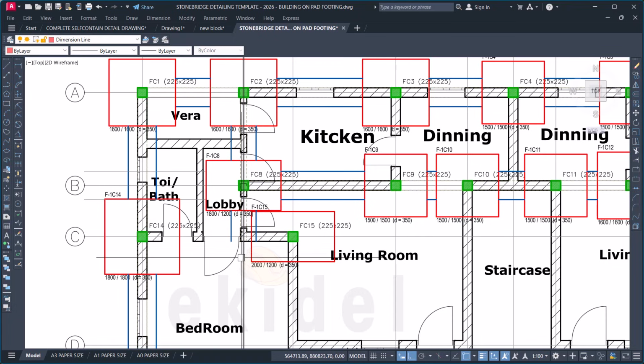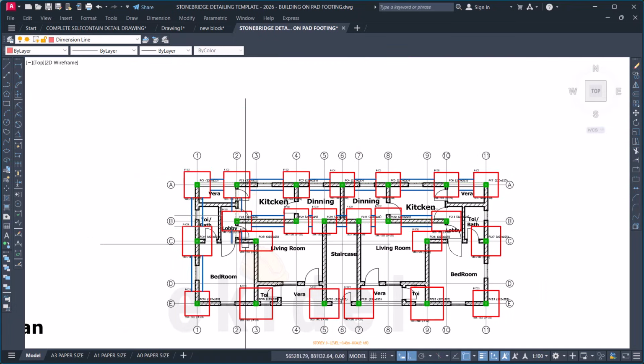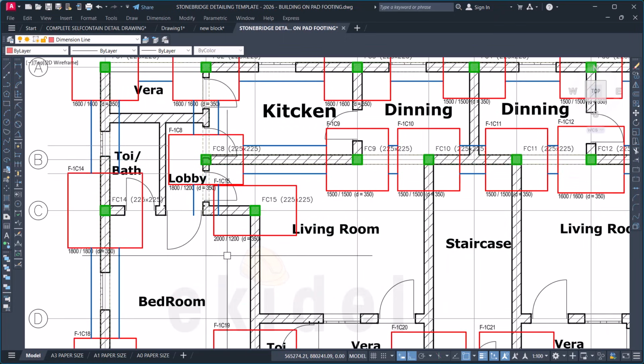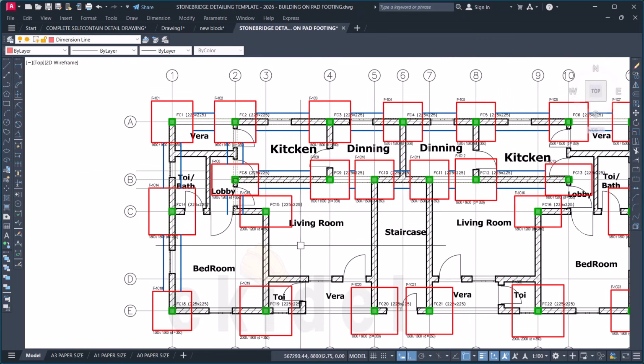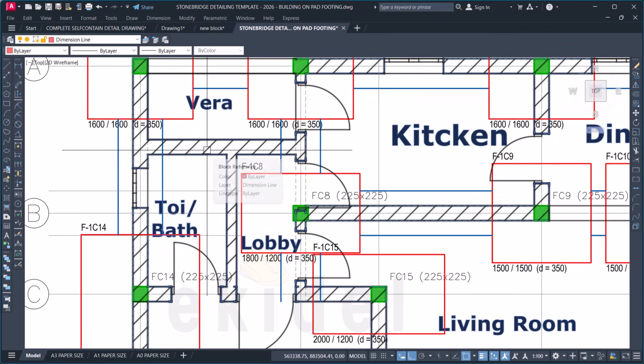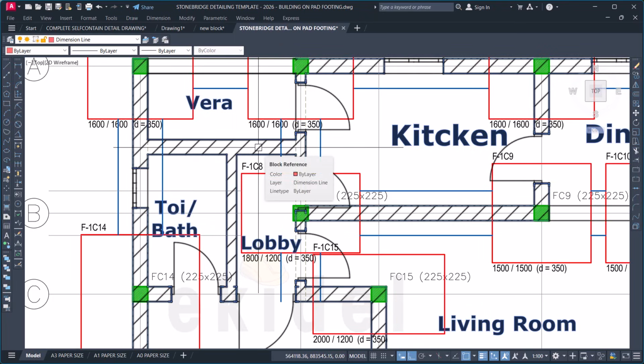Now when you're doing your digging or your trench line, just look at the major walls. When I mean by major walls, you can see that there are some walls that don't have grid lines. For example, this wall here. This wall is not a major wall. You can skip digging it because this is a toilet and a veranda wall. These walls can sit directly on the DPC without any issue. So you can choose not to dig this one.